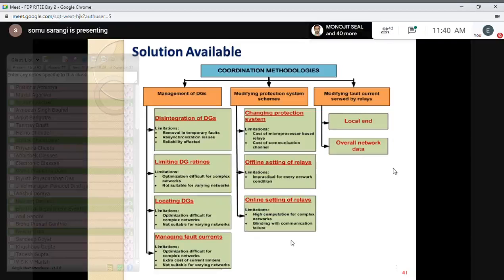By inclusion of the DG, the current magnitude has changed, and the control technique we have in our distributed generation inverter is also affecting the fault current. So all these techniques we are observing will affect the decision of a relay in our distribution system with inclusion of distributed generation. So that is a huge problem in our hands. Then how can it be handled, how can it be changed?